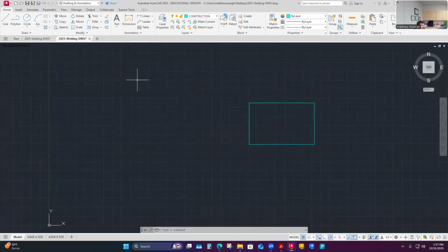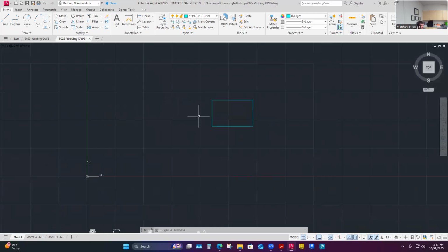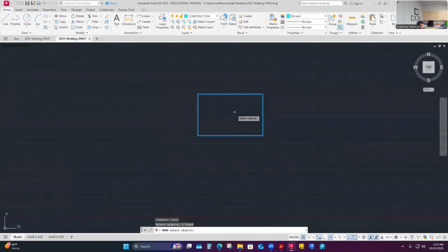And then one thing that we'll use a little bit here is move. Like if you've placed something you don't want it there, you can always move it pretty easily. Like the move command, you select move, and then it wants to know what geometry. I'm going to select just a single selection to select that rectangle. You know that you've selected geometry because a lot of commands will highlight lines like this. It goes that kind of neon blue. So that's pretty common, whether it's copy command, move command, or mirroring. You see your drawings kind of go electric, and that's electric. Oh, that's a good song.